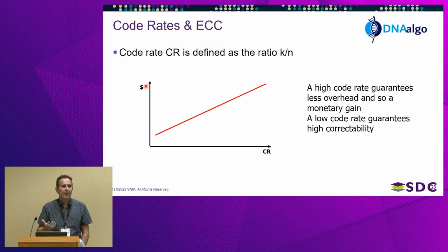If you have a code with a lot of correction bits, that is going to result in a situation of cost. It's more desirable to have a high code rate, where you have very few bits for error correction as a percentage of the frame size. So it represents essentially less overhead. A lower code rate means you're using a lot more error correction bits relative to the size of the frame. So the whole point is that there's an efficiency aspect to error correction codes, and we're mindful of that in the case of this application.